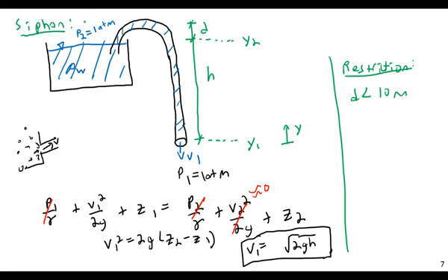What initially pushes the water up is not necessarily being pulled up. There's a vacuum being formed here, and atmospheric pressure is going to force the fluid up to the top of the tube, and then gravity takes it back down. But as we've seen before, air pressure can only push so far. It can only cause fluid to rise so high against a vacuum. And if you are greater than 10 meters, you're going to start pulling vacuum.